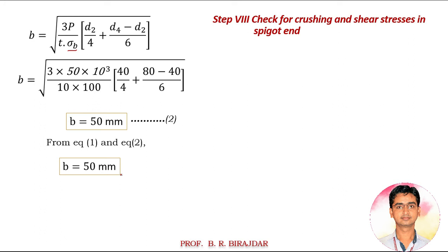But here we have to check whether it will sustain the compressive stress and the shear stress. If the corresponding compressive stress and shear stress are less than the allowable stress for these dimensions, then we can say the component which we have designed is definitely safe.